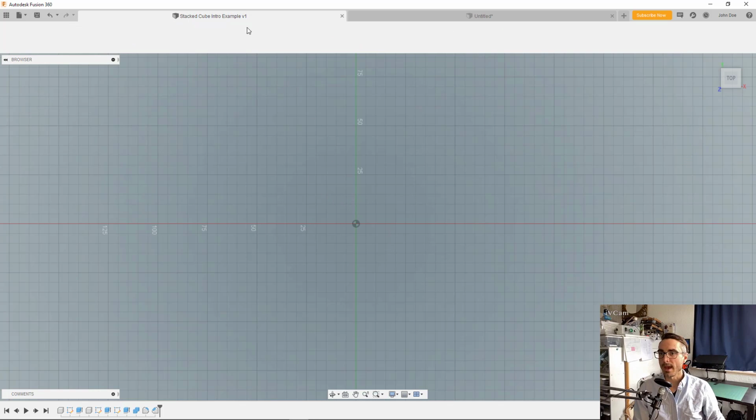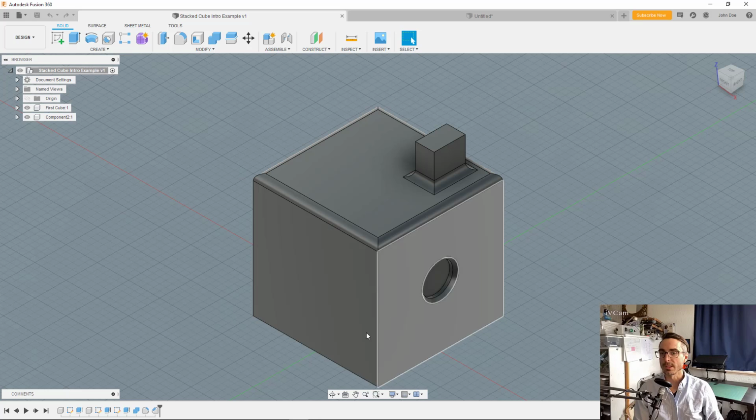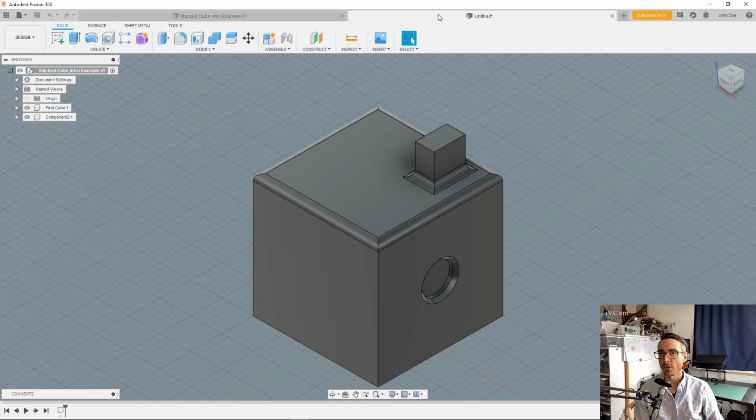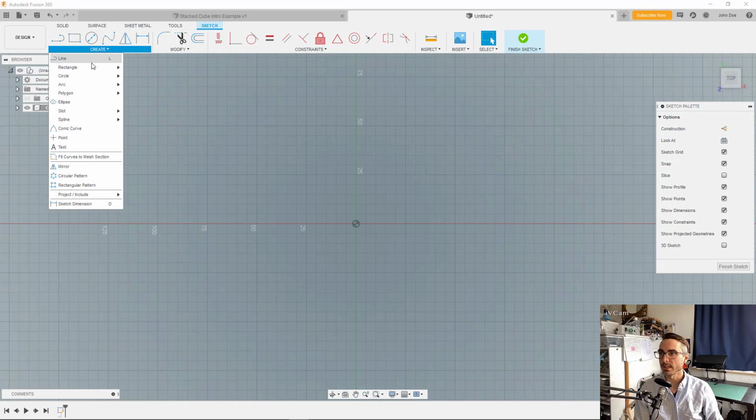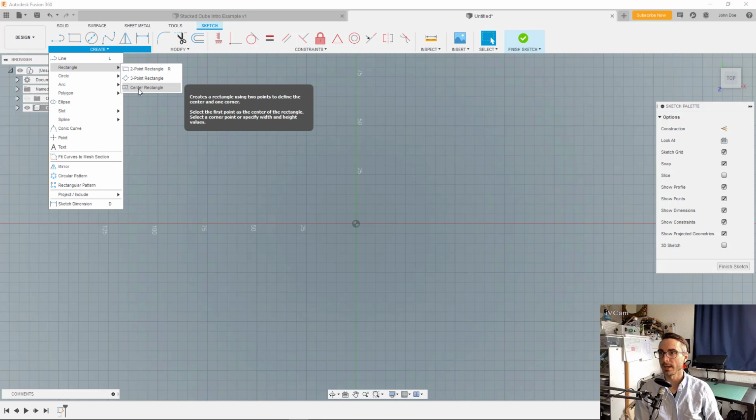The bottom feature that we have here is actually a cube, so I just need to make a square for the base that I can pull upwards. You've got a rectangle tool that we could use here, but I like to, as often as possible, keep my design kind of centered around the origin. This particular rectangle tool is drawn by snapping one corner to the other, but it doesn't really define where the center is. You'll notice that underneath this, I've got a whole lot more options for sketching different things, including a rectangle that is defined from its center. So I'm going to use that.